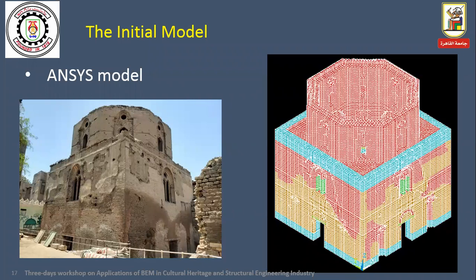Yes, actually, I'm sure you know that in order to do a finite element model, you can either use what we call a smeared model, which is using the entire wall as if it is one material, including the layers of the bricks as well as the mortar and everything. And this is more or less what we've used. We did not use a model that built the structure brick by brick.